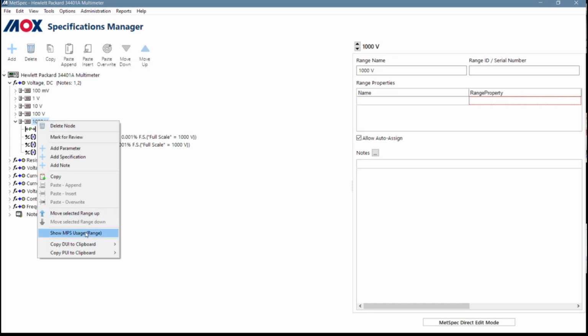Remember, Alex, we assigned these ranges to test points of data sheets as calibration standards, right? Now because I've done that, I can have it show me all the test points in the data sheets that use this as a standard, and it will include the TAR for that. So if I go through and everything's like 100 to 1 or better, I know I'm probably safe derating it.